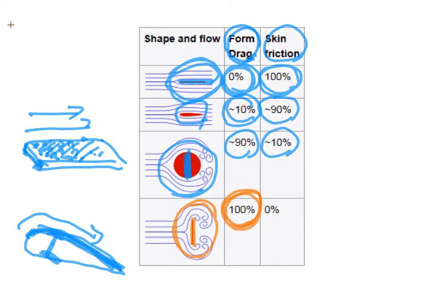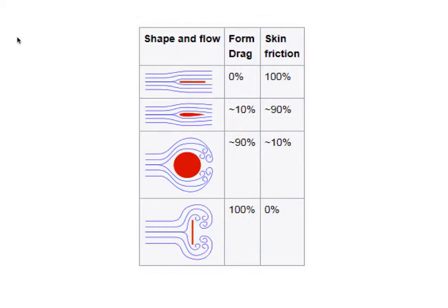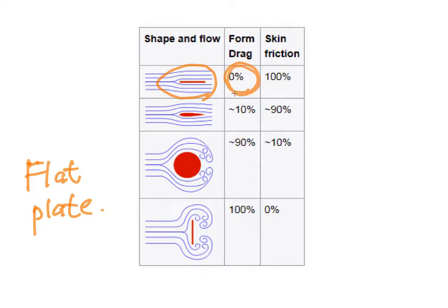So this is the idea. That's why in boundary layer, the examples and the theory are given using the idea of a flat plate. Why? Because we want to neglect the influence of form drag. The thickness of the plate does not influence the calculation, so we can focus on the shear stress that occurs on the surface of the plate.